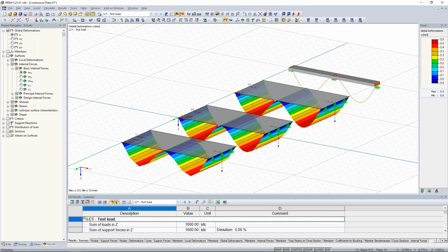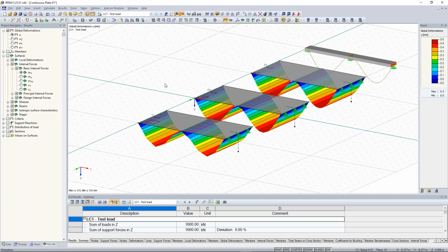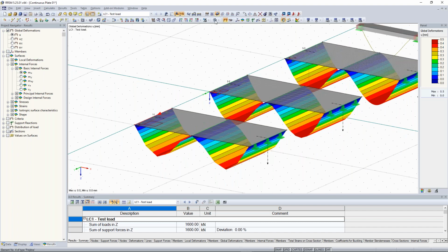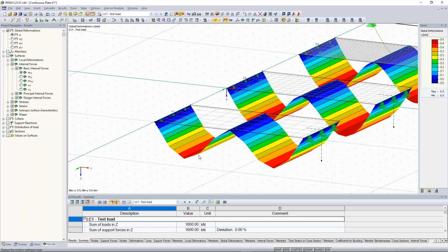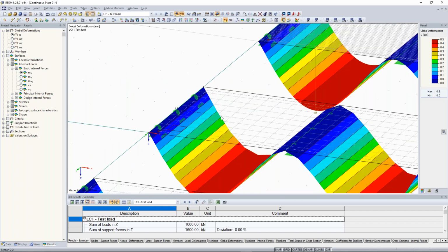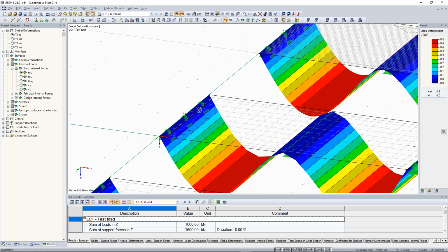And the first thing what we gonna see are the deformations. So here the deformation, and also very nice thing is when I change here the display model to the wireframe display model, I see here also the size of the FE meshes. And as we said before, here in this first surface, we have a FE mesh size of 1 meter, 0.5, and 0.1.